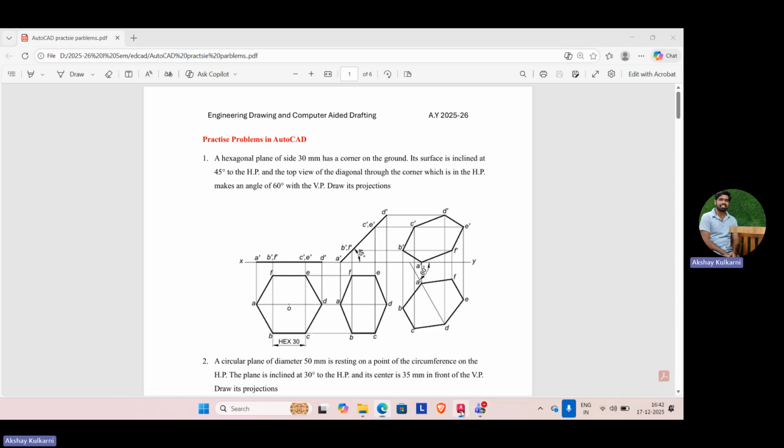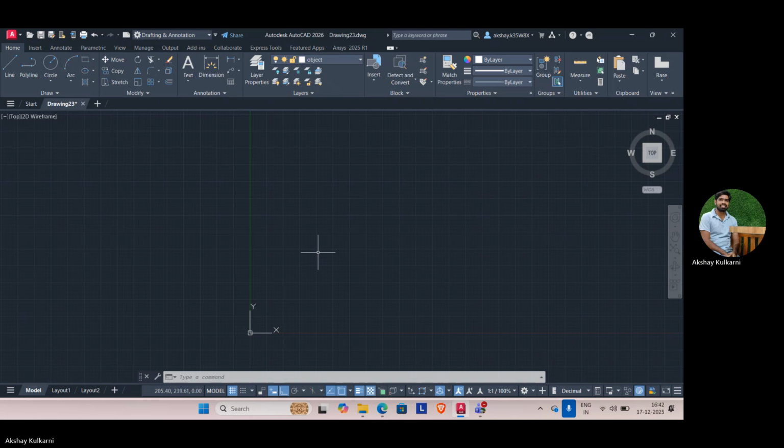First we'll go to AutoCAD. We'll create an A3 sheet. To create the A3 sheet, we are creating a border, and in that border we are keeping the diagram. To do that, first I'll select the rectangle in the draw command and bring the mouse on the black screen.